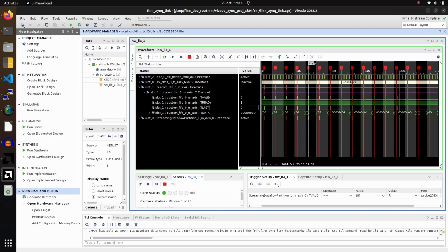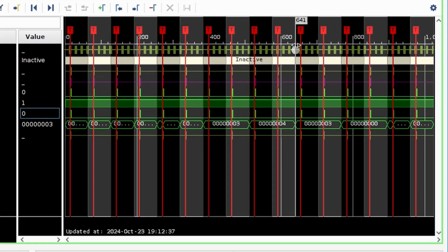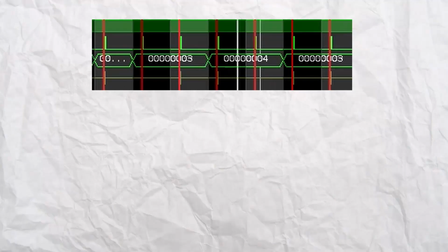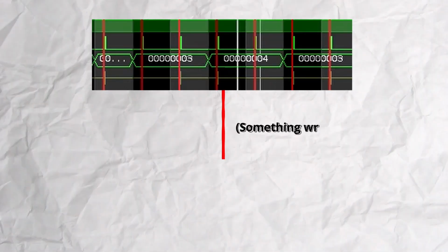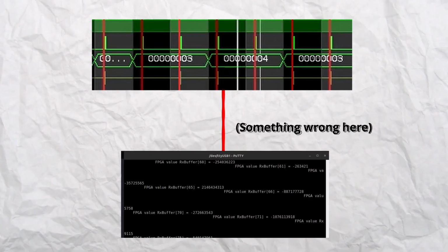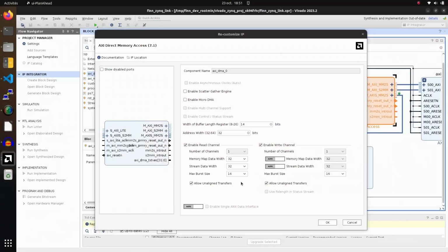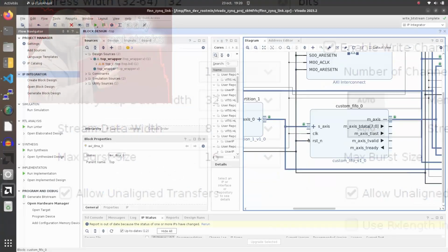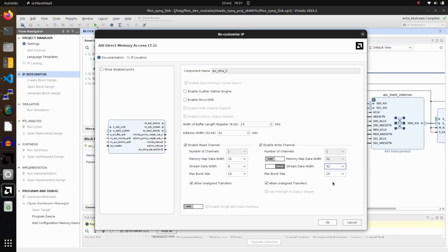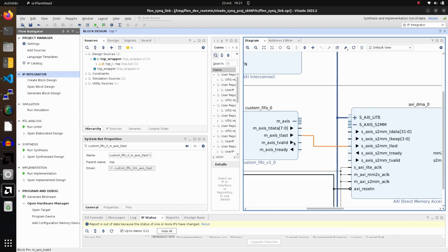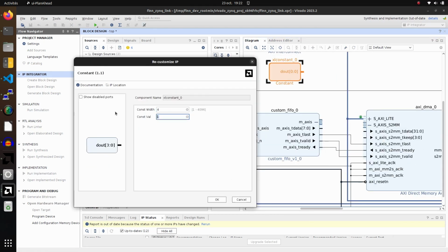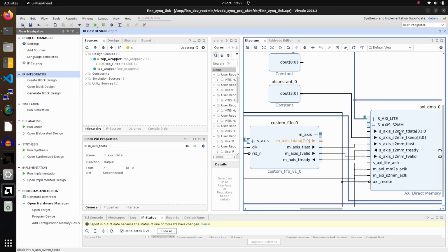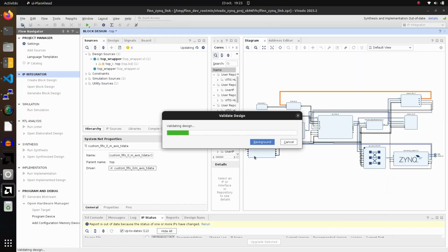After analyzing the signals, I figured the model did classify the sample right indeed. It's looking pretty good, actually pretty decent. But the data had some trouble making it through DMA, thus the UART giving me some very wrong values. My first instinct was to blame myself, and the way I tried to make DMA work with 8 bits. To solve this problem, I switched all of my configs back to 8 bits, except for the DMA that I switched back to 32 bits. To fix the data width gap between the DMA and the custom FIFO, I made the interface connection manually.